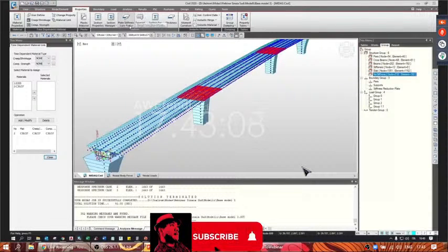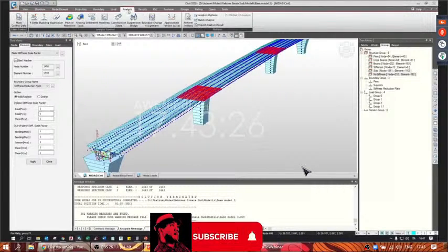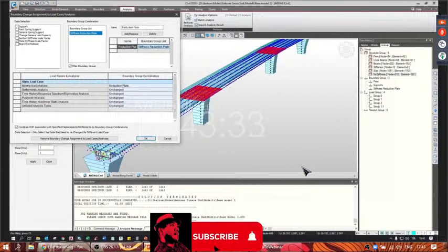To the plate stiffness scale factor, we also defined a stiffness reduction plate boundary group, and we put 0 on all these factors. This boundary group is useful to define for which load cases, here in analysis boundary change assignments, we are going to apply these modifiers. In this case, for example, we exclude the response spectrum analysis since it will not properly work otherwise. But we activate it for static load cases and moving load cases.